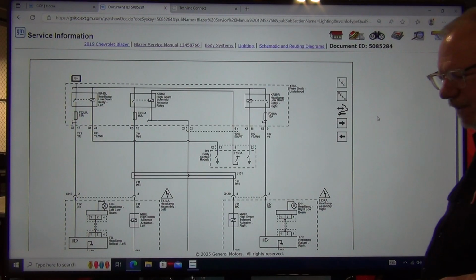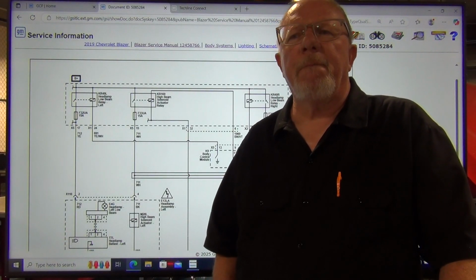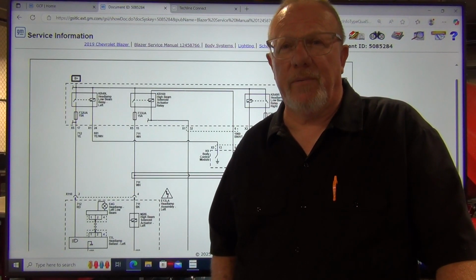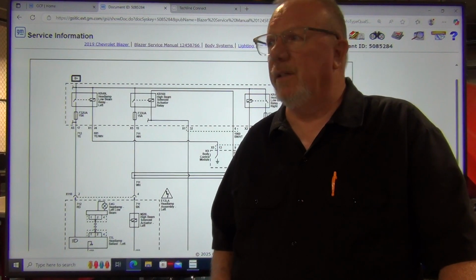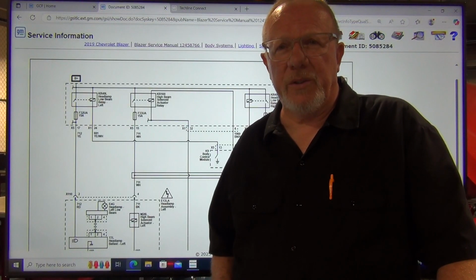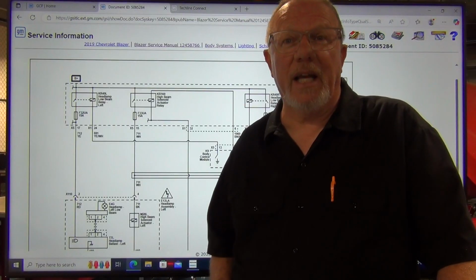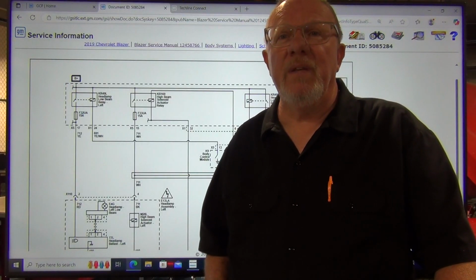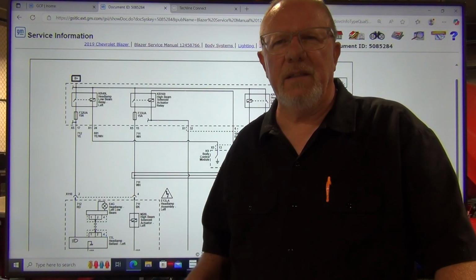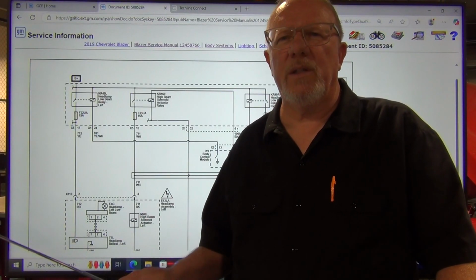Okay, so you'll hear me say this many times in class. In electrical repair, if I have something electrically that does not operate, okay, customer comes in and says my left front headlight doesn't work, okay? First thing I'm going to do is check and make sure it's the left front headlight, because sometimes people don't know left and right, okay? All right, that's just simple. So I'm going to make sure which light doesn't work. I'm going to look at it. I'm going to just functionally check it, see if the brights work, see if the dim works, or what's going on. So I'm going to get an idea of actually what's going on with the car.